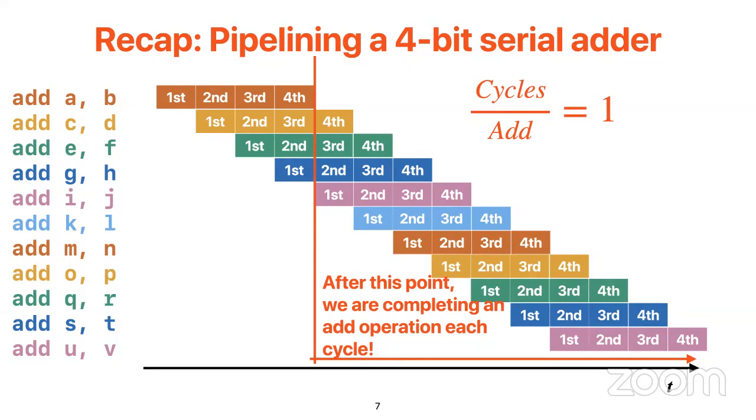If you can shorten the cycle time of the combinational part of your circuit, and you can duplicate it as multiple copies or divide the job of an operation into multiple pieces and still maintain a high clock rate, then with a sufficient amount of jobs, the average latency for completing each job, or the total latency of completing this huge amount of jobs, is going to be shorter than with the giant combinational circuit. We already demonstrated that in adders, and we have some questions that you practiced before on adders.